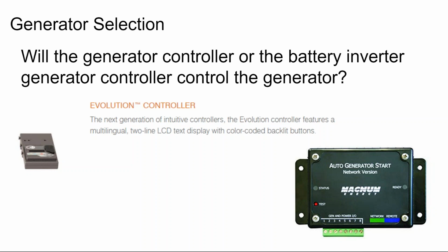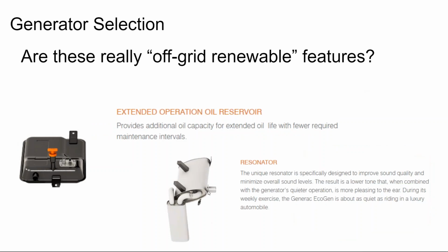That's the process of pushing more power into the batteries than they're really capable of, just briefly, in order to kind of clean the battery terminals. It's only something you do with sealed batteries. You don't do it with unsealed batteries. So we don't really need the controller because our inverters already have the controller.